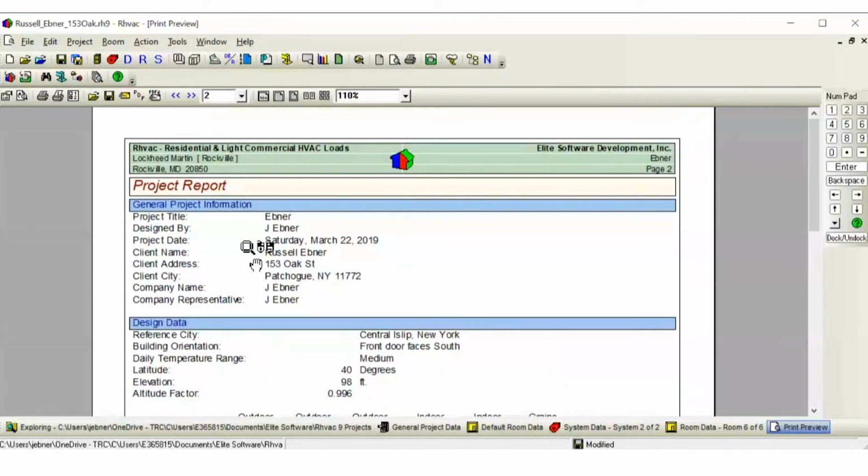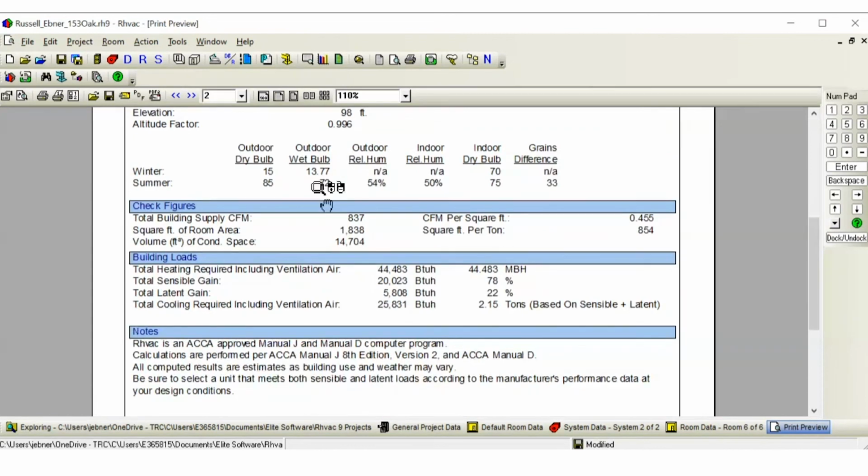The other thing I wanted to mention is on our worksheet, if you have a manual J that looks like this, 44,043 BTUs for heating, and say you installed 2 systems, 2 separately ducted systems, you would just divide the manual J BTU between those 2 systems so that it passes on the worksheet. So if you had 2 1.5 tons or 2 2 tons, you would just take this, divide it in half, it'd be roughly 22,000 and change. You put in 2 24,000 BTU systems and that'll pass.